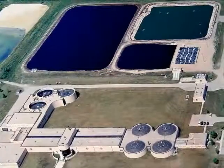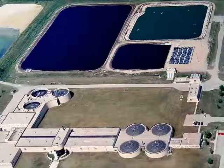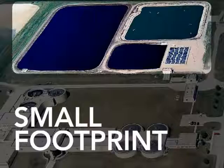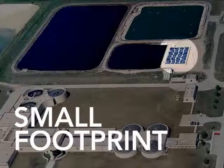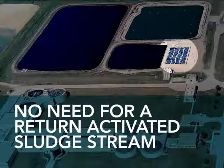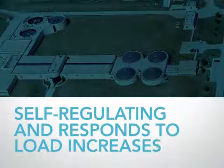With the MBBR process, operators can maximize treatment capacity while minimizing their footprint. An MBBR system is a fraction of the size of a conventional system and can be built without the need for a return-activated sludge stream, allowing for a single-pass process. Additionally, the Headworks BIO MBBR biofilm process is self-regulating, automatically responding to fluctuating organic loads without the need for operational